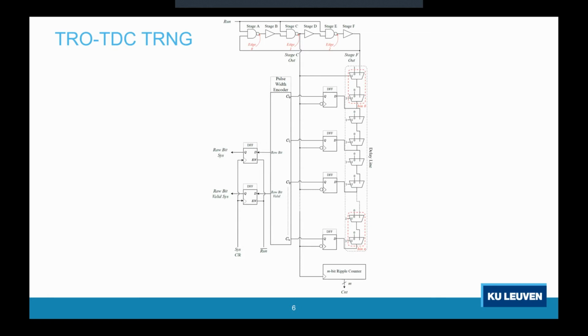And this is how it looks. The entropy source of this TRNG is a 3-edge mode ring oscillator, which consists of 3 inverting and 3 non-inverting stages. The 3 inverting stages at the same time inject the edge in the ring oscillator when the enable signal run is set to 1. These 3 edges will have identical mean period since they propagate through basically the same stages.